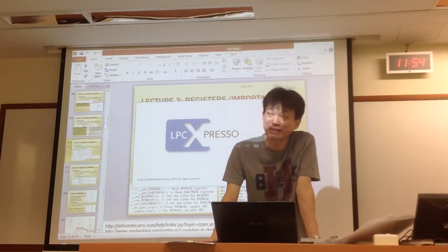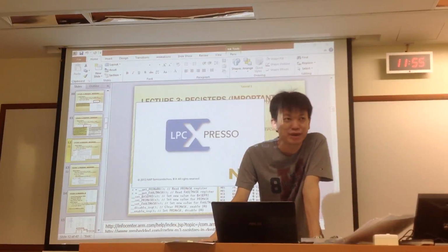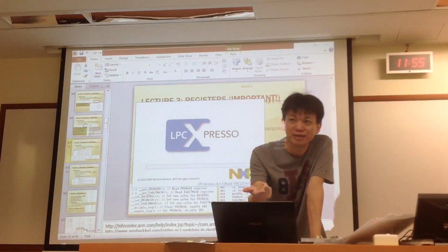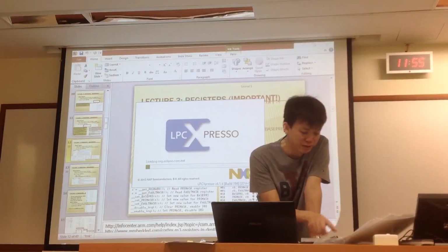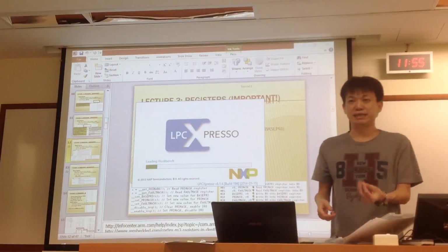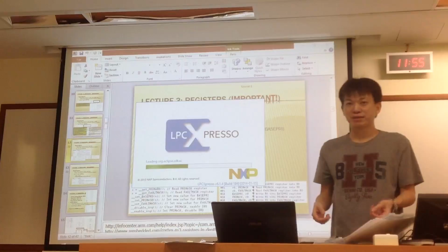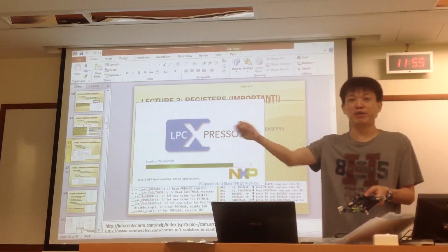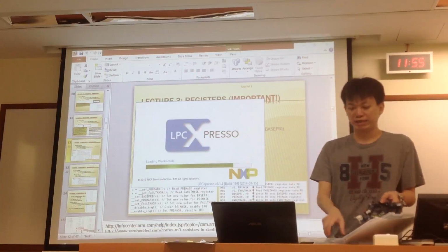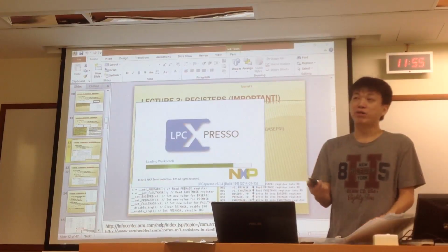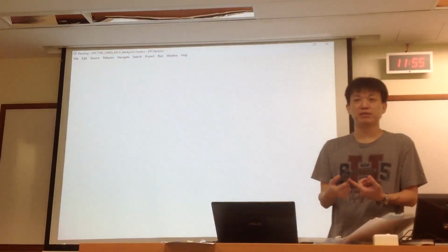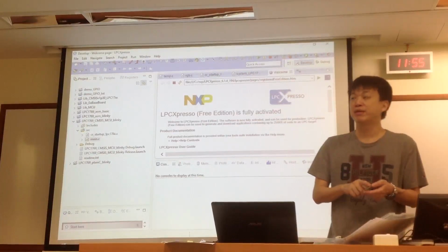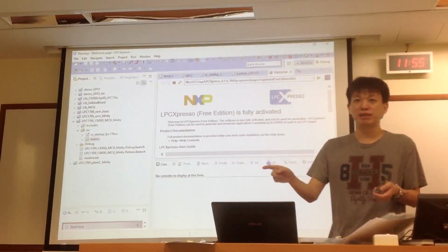Send a message. For I2C, they'll tell you how to set the mode, because you can be a transmitter or a receiver. Maybe your sensor is an input sensor or an output sensor. Like a light sensor is an input sensor. You read the value from the light sensor, so it's an input to the microcontroller, and your microcontroller should be the receiver. You try to receive.